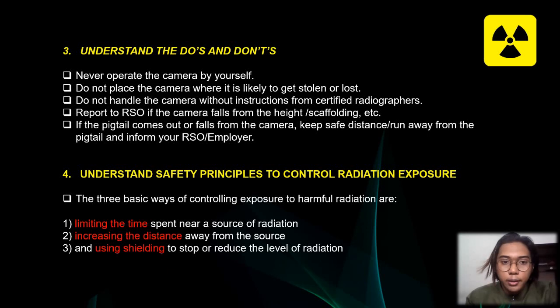If the pigtail comes out or falls from the camera, keep a safe distance or run away from the pigtail and inform your RSO. This is because the pigtail is where the radioactive assembly is. Even when the camera is not operating, the radiation is continuously emitted. So it is important to make sure the pigtail is always inside the camera.